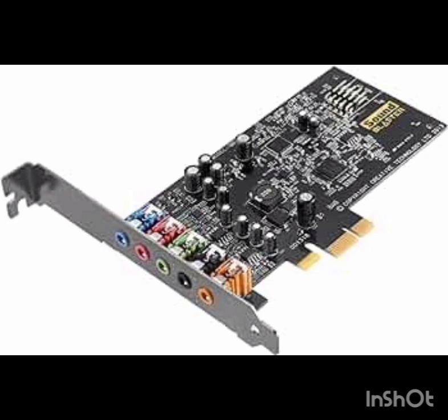Technical specifications. There are a few main technical specifications for sound technology. The first is bit depth, which is the number of bits used to represent the sound data. A higher bit depth results in better sound quality. The second is sample rate, which is the number of samples per second used to represent the sound. A higher sample rate allows for a higher frequency range and better sound quality.